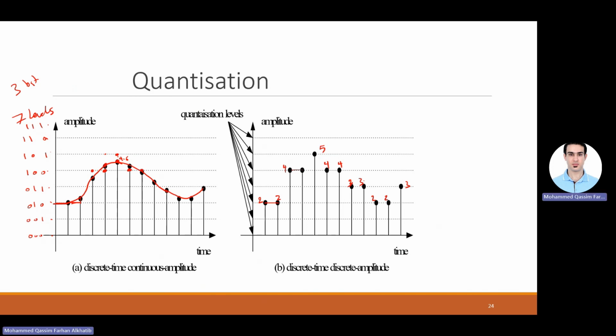All right, so that's what quantization is. Is it clear? Sampling into quantization. With sampling, I have the samples with the actual values, but at discrete points in time. Now with quantization, I will have discrete points in time and discrete points in value. I'm limited to a set of values. Instead of having 4.6, I will have 5.